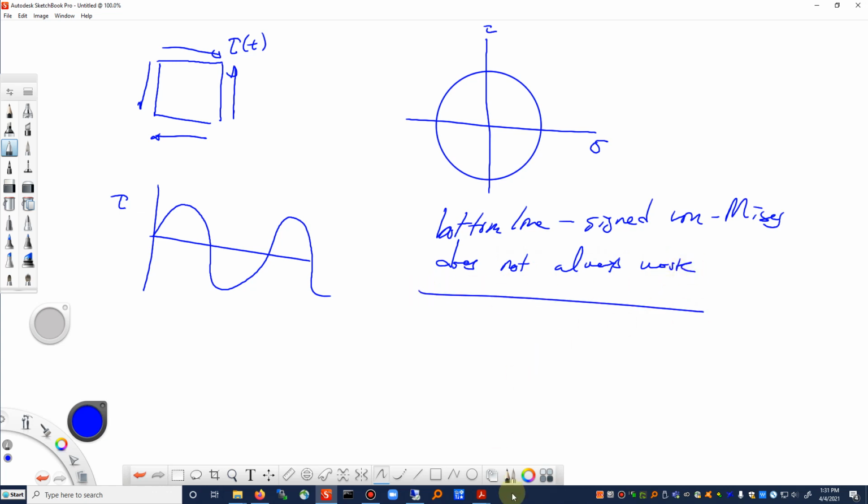So be real careful with that. And I only teach this because I've seen this kind of thing out in the wild. People do have this option sometimes in fatigue analysis software to do a signed von Mises fatigue stress calculation. And generally, I think you want to avoid it unless you are very careful and understand what some of the pitfalls are with using the signed von Mises. Non-proportional loading has its own can of worms that come into this as well. But even for proportional loading, it is usually a better thing than a signed von Mises.